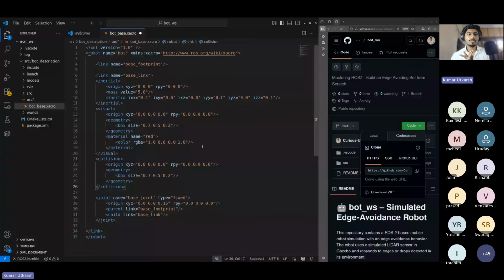If we want to do a repetitive task in code, we don't write the logic again and again. Instead, we create a function for it, and we send the parameters, and the one segment of code gives the output to us. So in XACRO, you can create functions. If you want to define multiple links, and the entire chunk of code is the same, just the values are changing, you create a function with variables, call that function, and only change the variables, and the output remains the same. So these were the two main reasons for using XACRO.